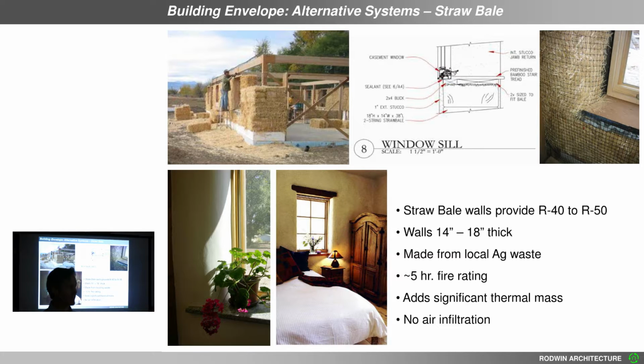The reason is because even though the bales themselves are cheap and your labor is inexpensive, you've now made a wavy wall. And if you ask any tile guy or cabinet guy or anybody who's touching those walls, electricians, plumbers, anybody else, they'll say, wow, that's really hard to work with. We're going to have to get our best artisans in, not just our lowest paid guy, but our best, most knowledgeable tile guy or cabinet hanger to work with a wavy wall. So you're making something that's very custom, very handcrafted, essentially.